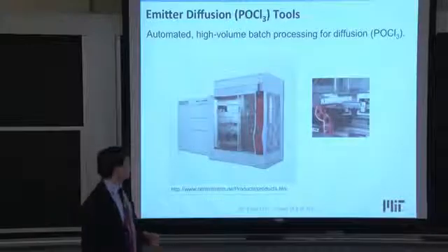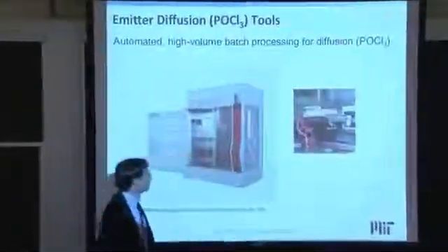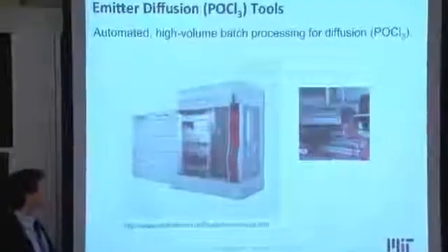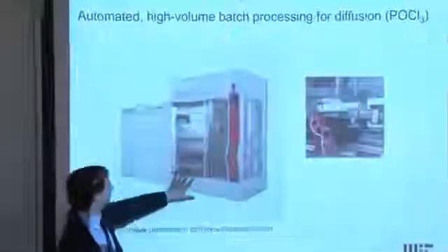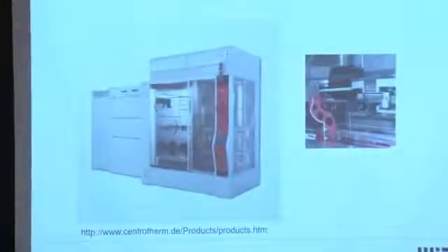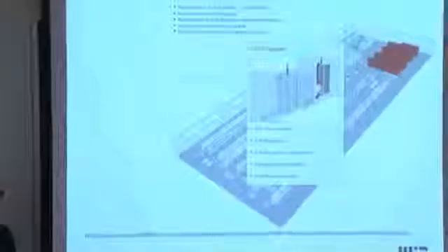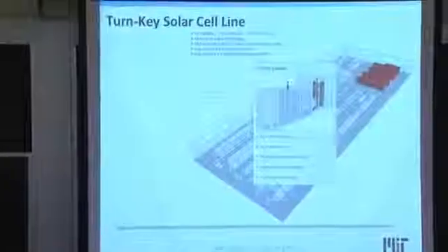And here's an example of Czochralski wafers being loaded into the phosphorus diffusion furnace and then out again, just showing the degree of automation in some of these furnaces. This showing a stack not dissimilar from the one in the laboratory downstairs in building 35, where we'll be doing our phosphorus diffusion.